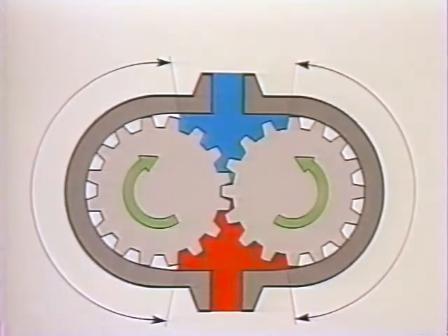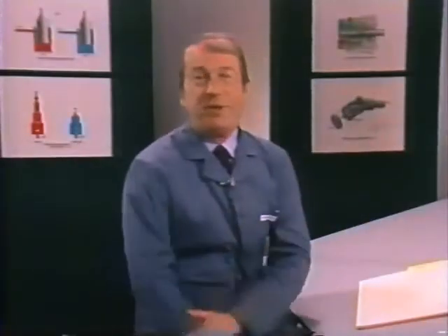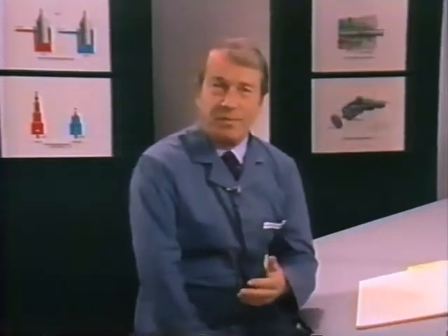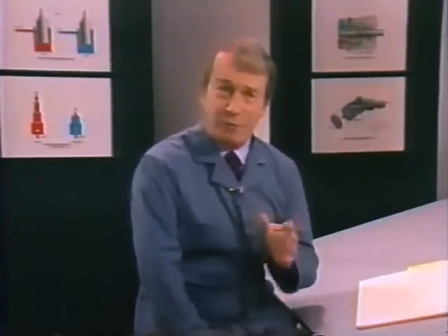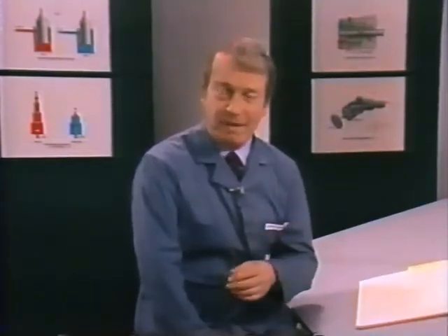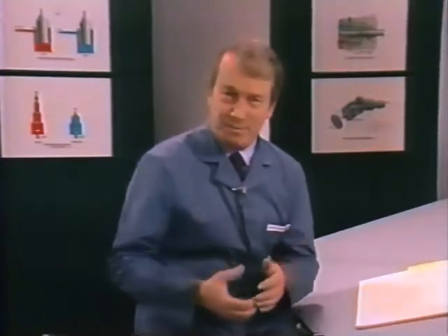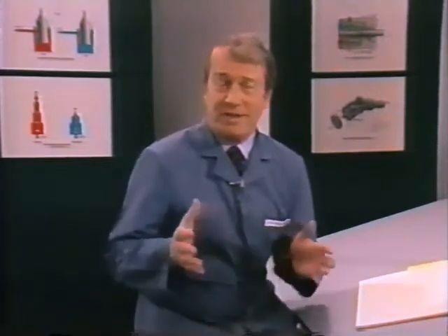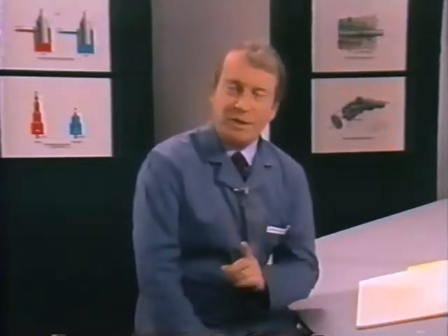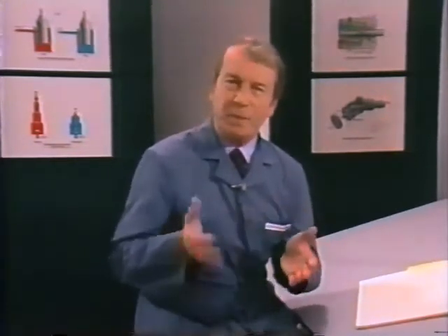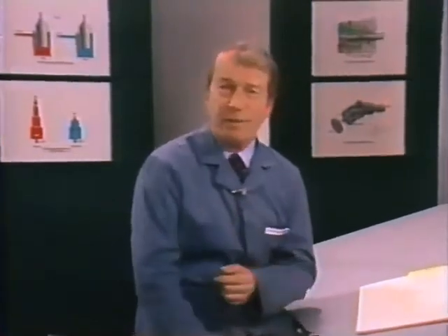Segments of the two meshing teeth tend to oppose them, so we have the effective area of approximately just one tooth providing the torque. The speed of a motor is determined by its displacement and the flow rate of the fluid driving it. Small motors with a given flow rate operate at a higher speed than large motors with the same flow rate. To reverse a motor, we simply direct the pump flow into the opposite port.